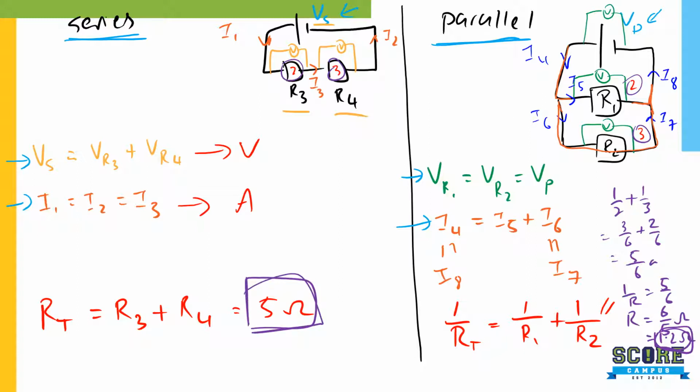Another advantage of having a parallel circuit over a series circuit is that in a series circuit, if, for example, instead of using resistors, right, let's just say you're connecting bulbs. If this bulb blows over here, I mean it fuses, this bulb here will not be able to light up. So imagine your house and one bulb blows. Because of one bulb blowing, the entire house is in a blackout. You wouldn't want that. And that's why most likely the lighting in your house is done via a parallel circuit, whereby if one bulb blows, the other bulbs can still light up.